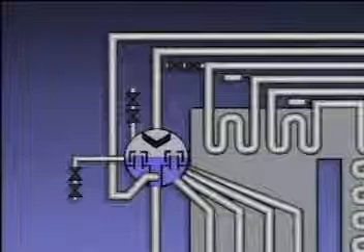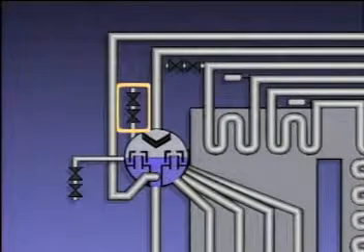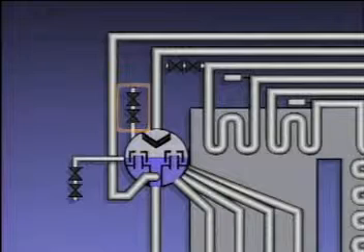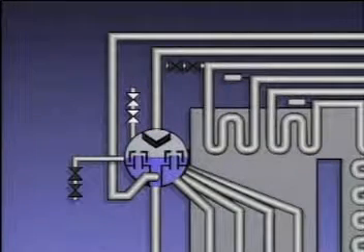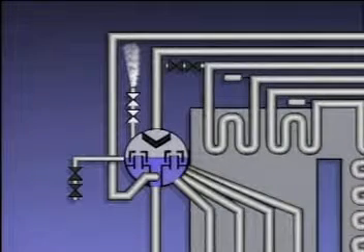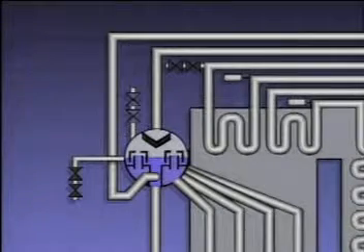Boilers have a number of vents, drains, and blowdown valves that are open to allow air, water, and contaminants to be removed from the boiler. As an operator, you should know when each vent, drain, and blowdown valve should be opened and when each must remain closed. Vents, such as this boiler drum vent, are usually located on the tops of components. Vents are usually opened only during a boiler startup, when there may be a great deal of air in the system. The vents are needed to bleed air from various components.